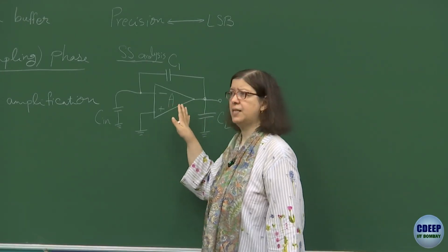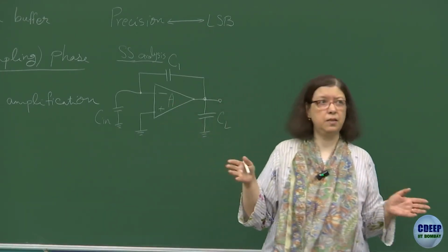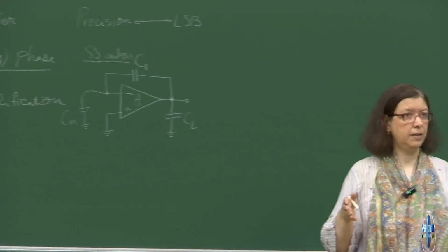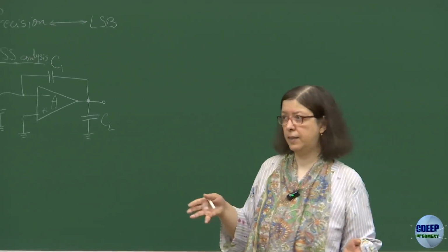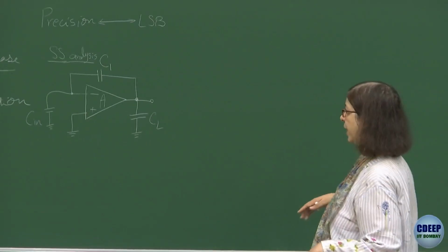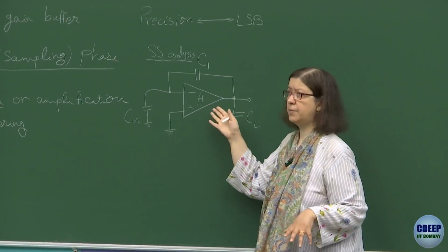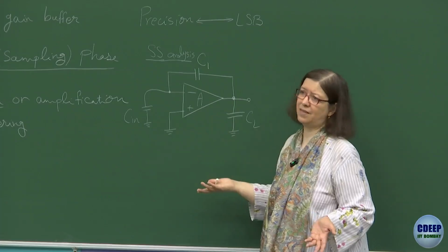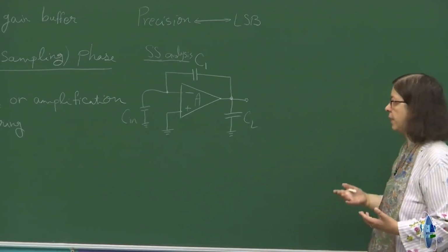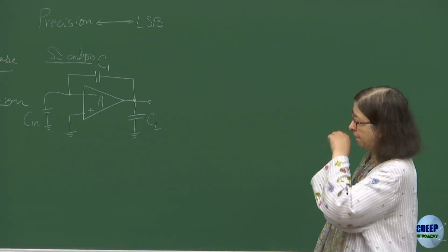One thing also is that sometimes slewing is the major contributor to the delay. This is also very important, but still we cannot have a limited gain or limited speed because that will have an impact on the precision. So anyway, we need to have a proper op-amp.